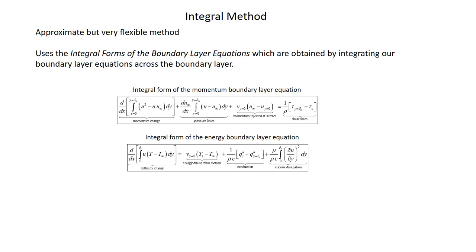Today we're just going to give kind of an overview or an introduction, and then next week we'll dive into more detail about actually using these techniques. So the basis of the integral method is the integral form of the boundary layer equations. So we'll come back to these, but basically we're going to take our boundary layer equations, which are our simplified governing differential equations, and we'll integrate them across the boundary layer.